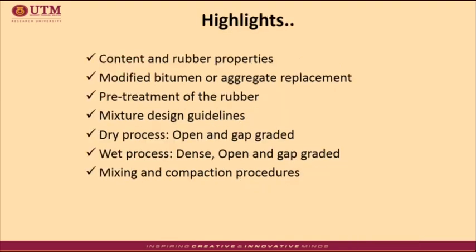These are some highlights of what we have discussed on rubberized asphalt. It should be noted that the content and rubber properties determine the final mix performance. The modification technique is based on either modified bitumen or aggregate replacement. And then, either it's cup lump or latex or crumb rubber, it should be pre-treated before use.